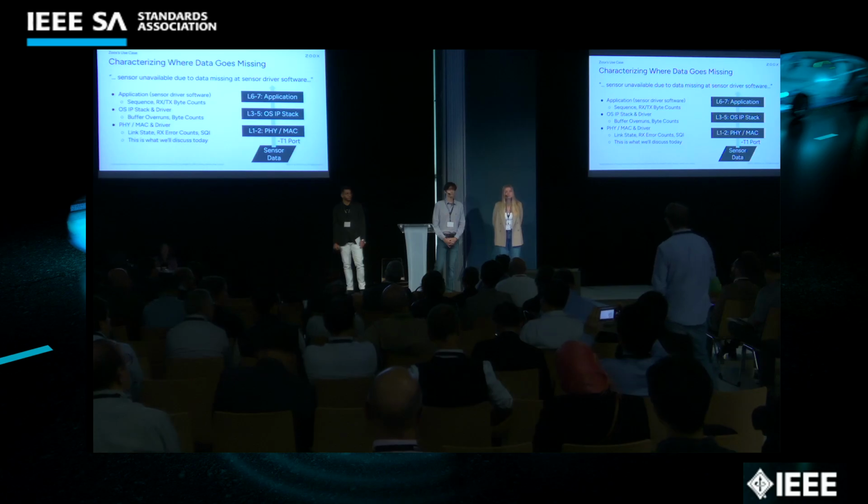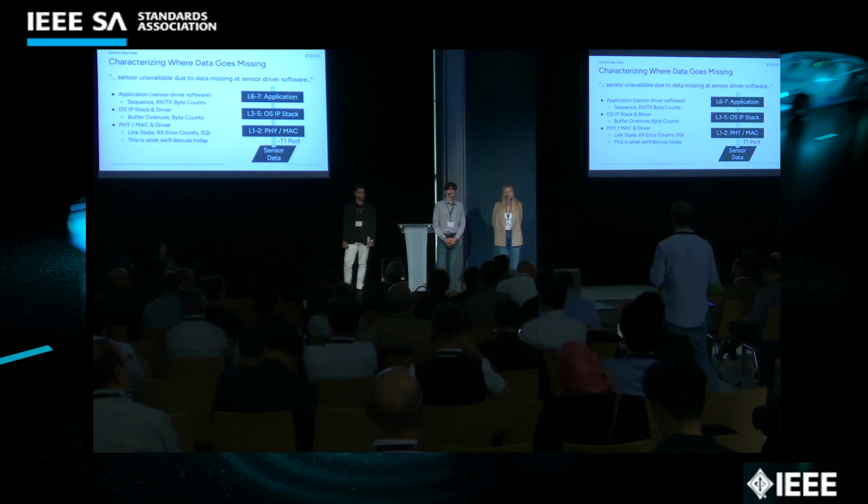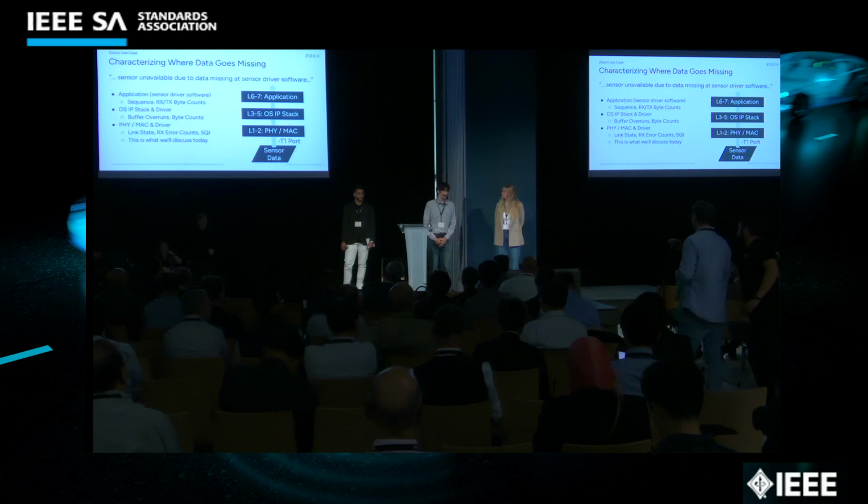And the second is the link status is sometimes deliberately kept up for some time because you have events like ESD or EMI, which are tampering with the link quality. So the PHYs keep trying to establish link without losing it while it's not really available. So that's probably what you are seeing. That's something which is done not by accident, but really on purpose.